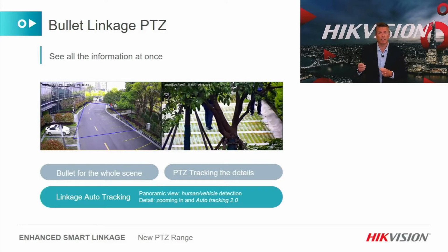Once they leave the scene, the PTZ camera, because it's got quite a powerful 32 times optical zoom on it, can see beyond that fixed view that we've got and it can carry on. So it can take over and then start using the smart tracking. You could have had that PTZ set up on a patrol, so using the full 360. So you've got it panning around behind the camera, zooming in and out of different spaces, but the fixed camera has absolute priority. So any alarms that come into that area, the PTZ will stop its patrol, zoom round and start tracking what you've asked it to track.